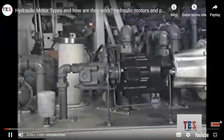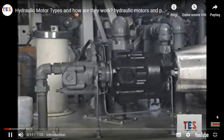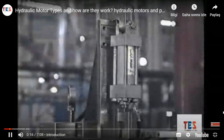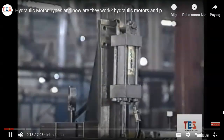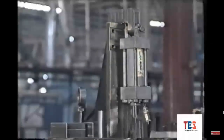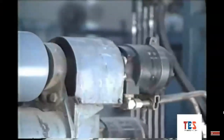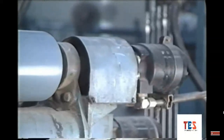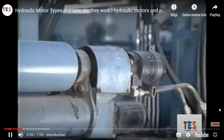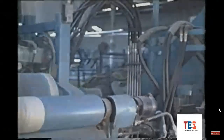In a previous lesson, we saw that pumps convert the mechanical energy of a turning shaft into hydraulic energy in the form of pressure and flow. This pressure and flow can be converted into linear mechanical force by cylinders which apply force in a straight line to extend or retract a cylinder rod. In this lesson, we will see how pressure and flow are converted into rotary mechanical force by hydraulic motors. We will also see how the efficiency of motors can be changed, so the force they develop can match the work being done as closely as possible.